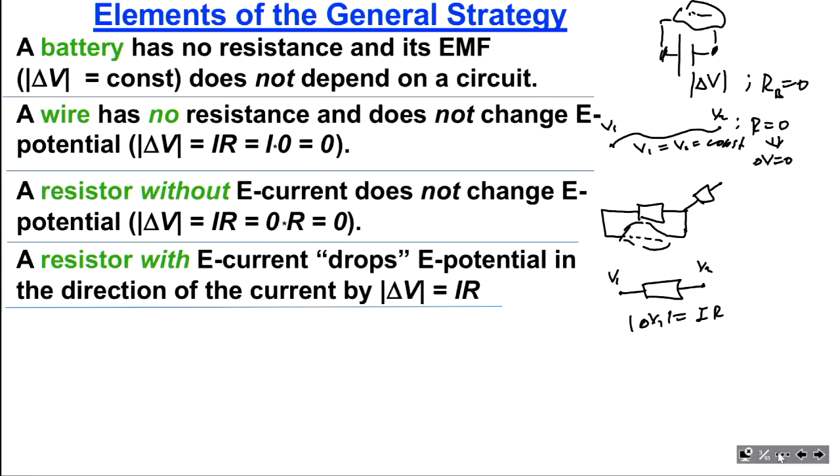And here only one end is connected, the second is not, which means electric current has to be equal to 0, because the electrons cannot travel through, they cannot leave that end. And because electric current is now 0 for this particular device, first of all, it doesn't affect the rest of the circuit. We can just remove it.